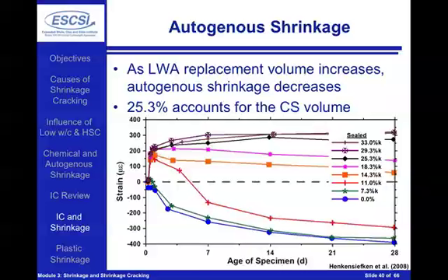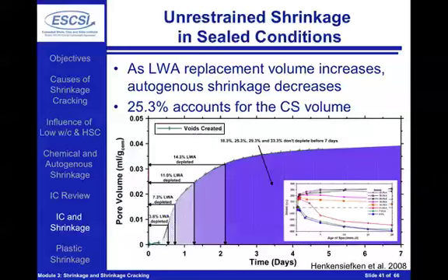And if we add in additional internal curing water, we're not going to see any additional improvements after that particular time. The takeaway, though, plain concrete, autogenous shrinkage, no drying taking place, but just shrinkage taking place because of these vapor-filled spaces that are forming due to chemical shrinkage resulting in self-desiccation. Adding internal curing water has benefits. If we make sure that we add the right amount of internal curing water, we'll see a slight expansion and then essentially no shrinkage as long as the concrete stays sealed.